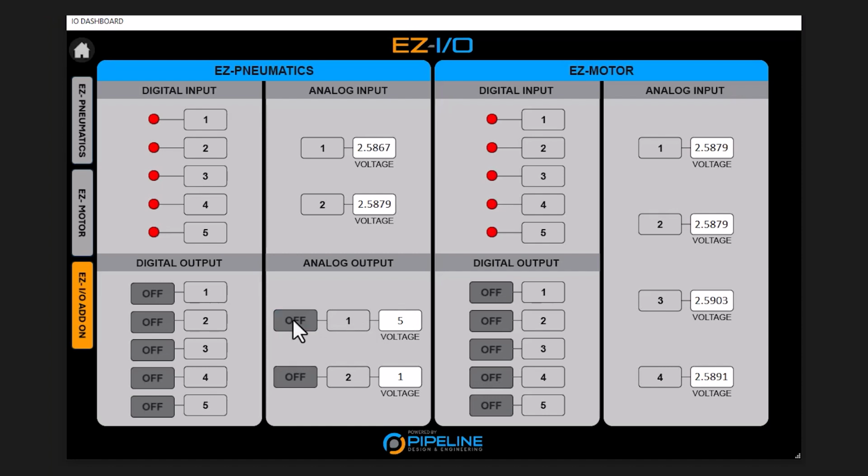Finally, the computer must remain on and connected to the control box at all times for sequences to continue running. If the computer is disconnected, the motion sequence will terminate immediately. Reconnecting the computer will not resume the sequence. Instead, the user will need to start a new sequence once the computer is reconnected. Therefore, it is recommended that users configure their computer settings to prevent interruptions, such as the computer entering sleep mode, installing updates, or restarting automatically.